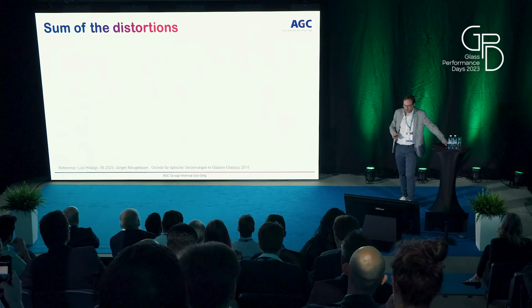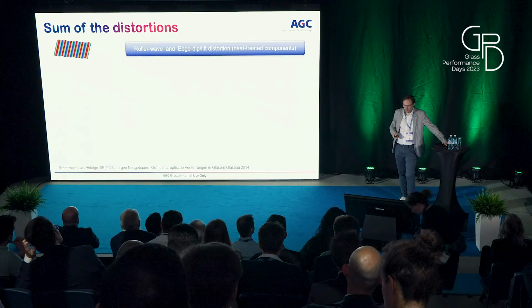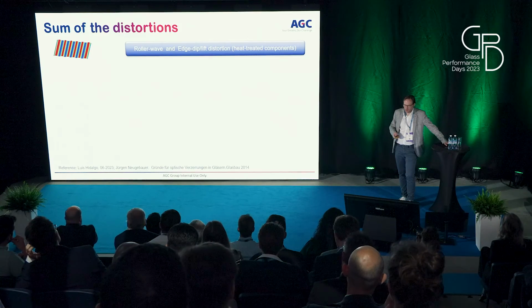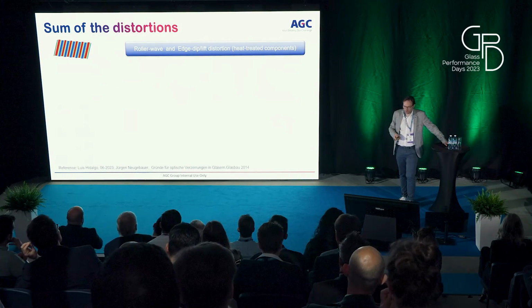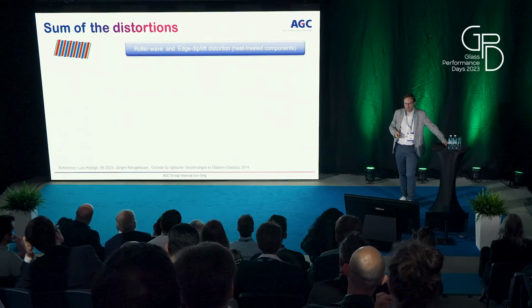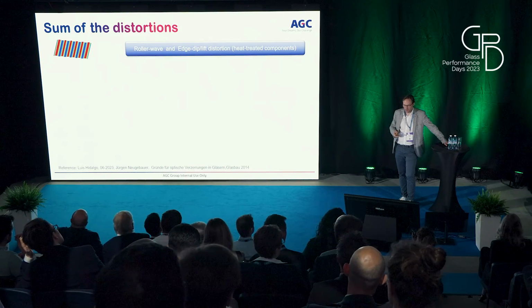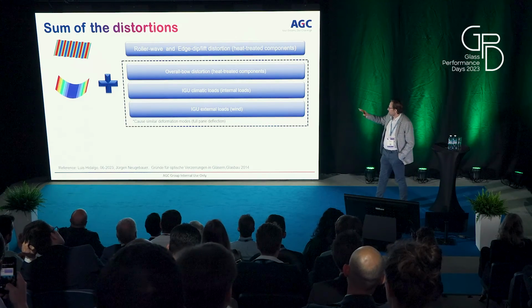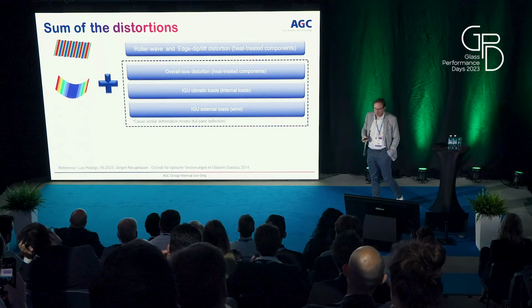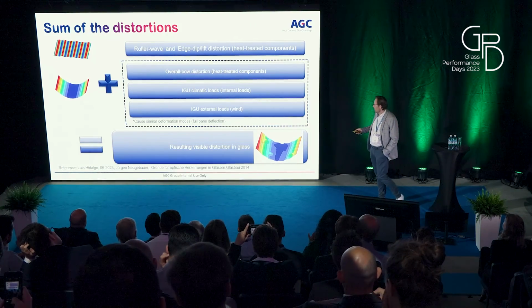If you sum up the types of distortions, we have the roller wave and edge dip, edge lift distortion components, I would say, of heat-treated glass. It does not matter if it is a fully tempered glass or a heat-strengthened glass. But we have also others. We have the overall bow, the climatic loads, and additional external loads like wind loads. And all this comes together in an overall deformation.